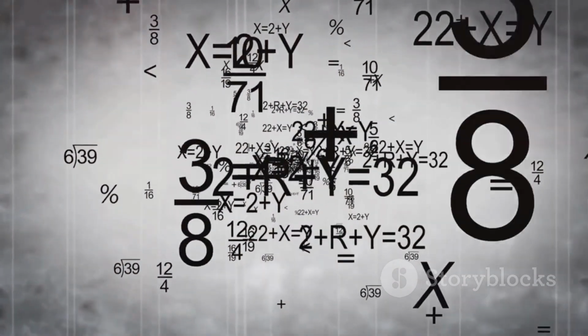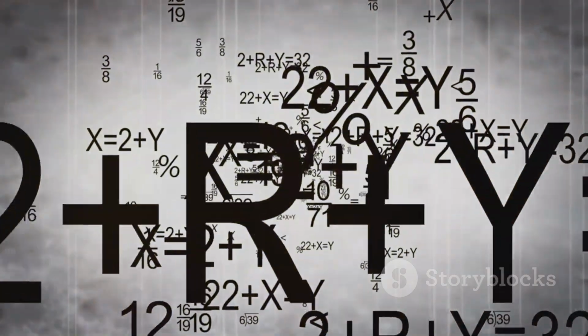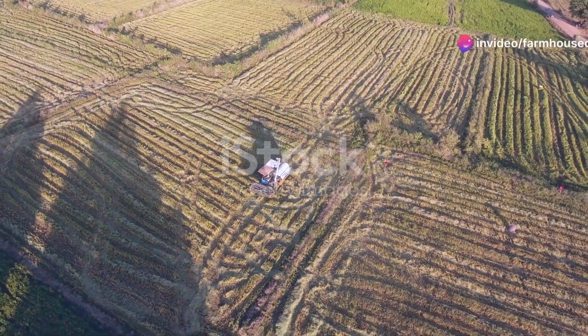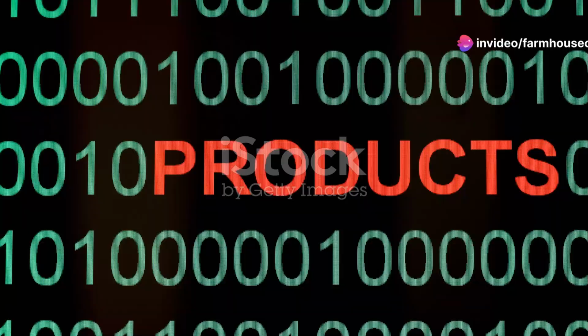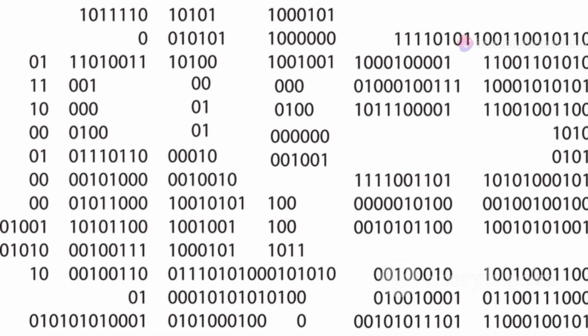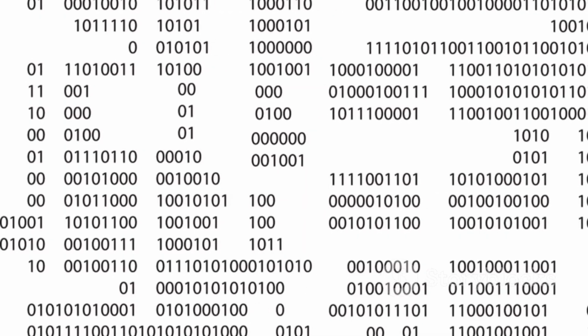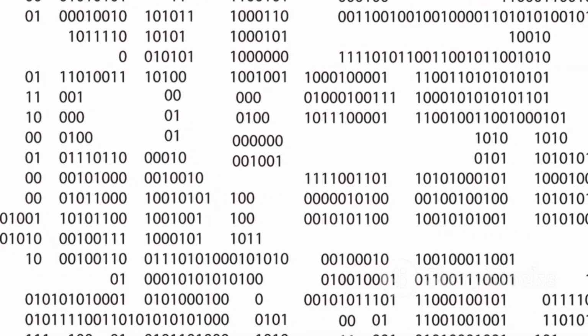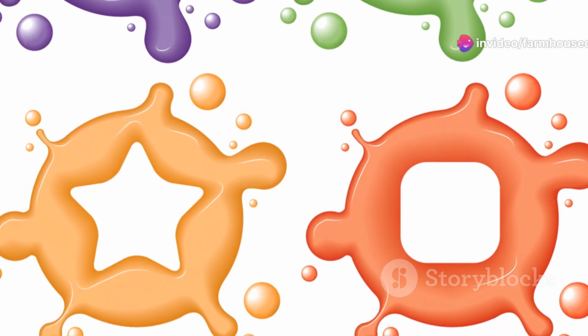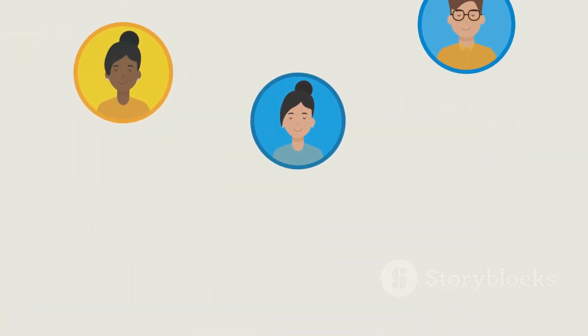Section 5. From groups to simplified expressions. Once we have formed the largest possible groups of ones, we derive the simplified Boolean expression. Each group represents a product term in the simplified expression. The variables included in the product term are those that remain constant within the group. For instance, consider a group encompassing 4 cells where the variable A is always 1, but B and C change. This group translates to the product term A. We repeat this process for all groups.